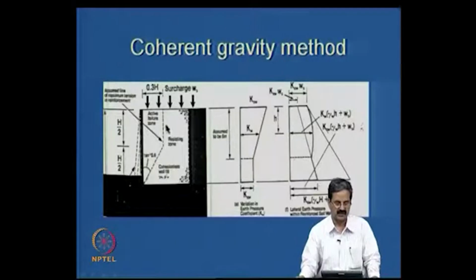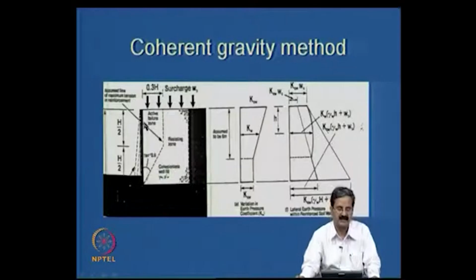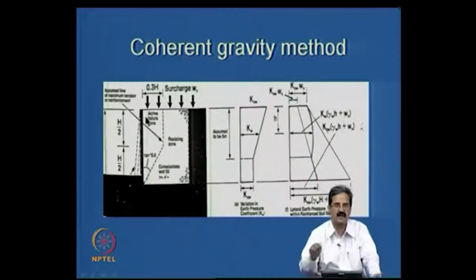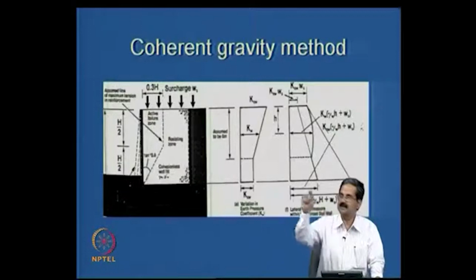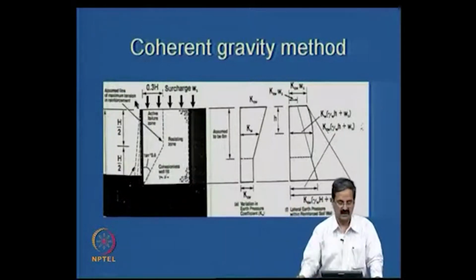So that's what it means. People have constructed this using finite element analysis or experiments. People have measured using a centrifuge, where you can put reinforcement and measure its tensile strengths. At this point, the point at which it is maximum, we have seen one even in the Binquet and Lee method, where they assume some maximum strain distribution, and we made some assumptions there. Similar to that, we have the location of strains here, so it will be like that, right.